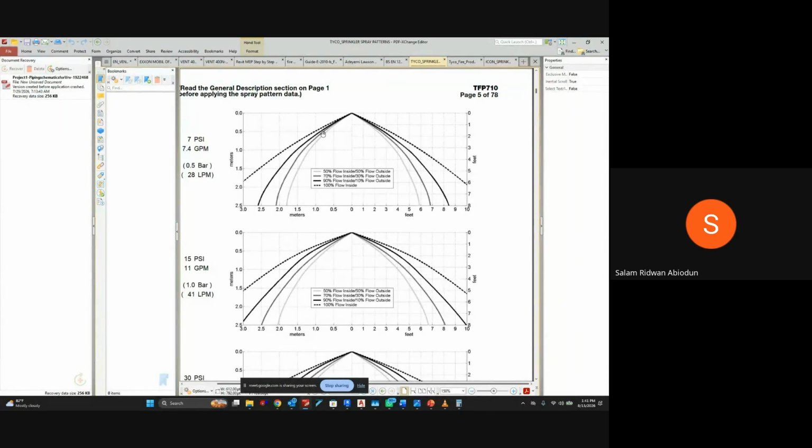I say the more sprinklers, the more safety factor. That is what they are saying now. They say if it is high hazard, you should consider one sprinkler to have 9 square meters. And if you are using a 100 square meter space, you are going to have more sprinklers in that place.